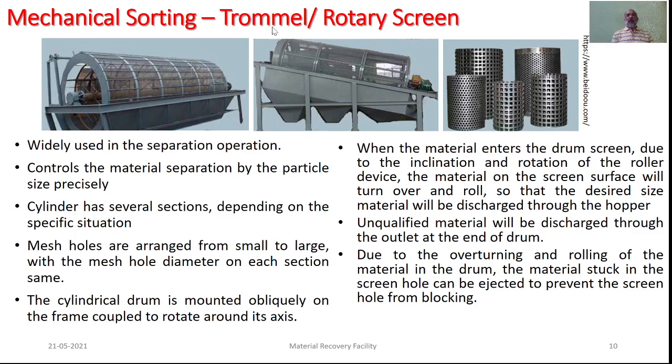This trommel or screen controls material separation by particle size, based on the size of the mesh employed in this cylindrical shape. The cylinder has several sections depending on the specific situation. The mesh holes are arranged from small to large, with the mesh hole diameter in each section kept the same.